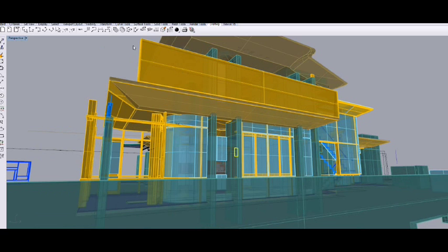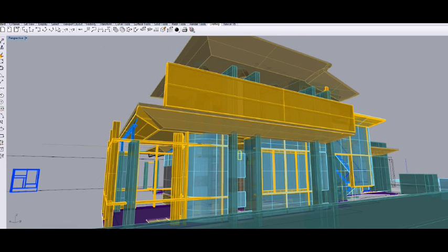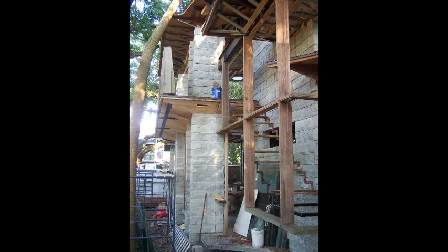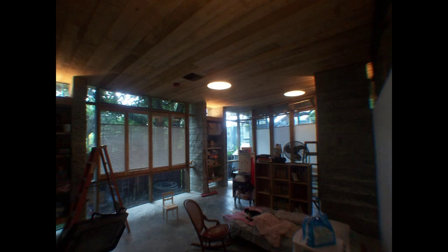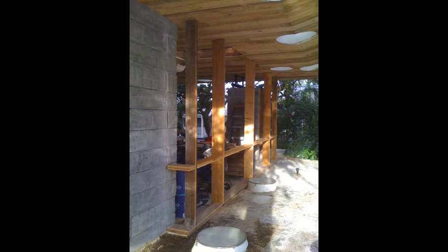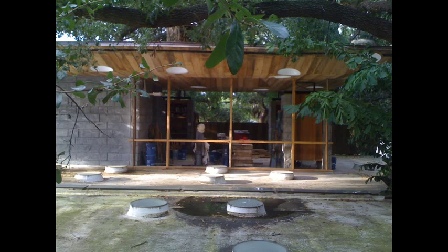So you can see, with that as the basis for designing all the pieces, we can do things like design this piece of curtain wall that hangs from above and is supported and cantilevered off of a stair frame. In this case, we have the lower edge supported by the concrete floor, the top edge is embedded in the ceiling and supported by that. The jamb here is embedded in the concrete block wall, and you end up with a very simple, thin system here that really does what it's supposed to do, and that's recede.